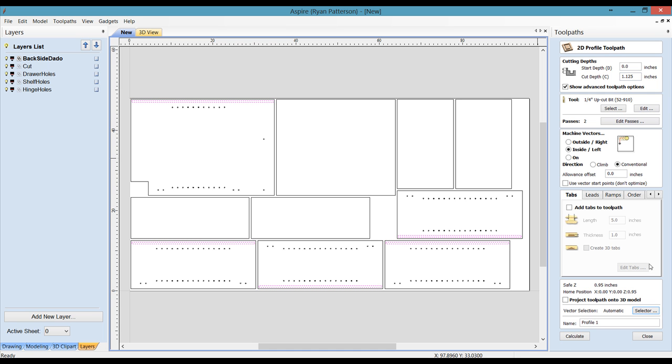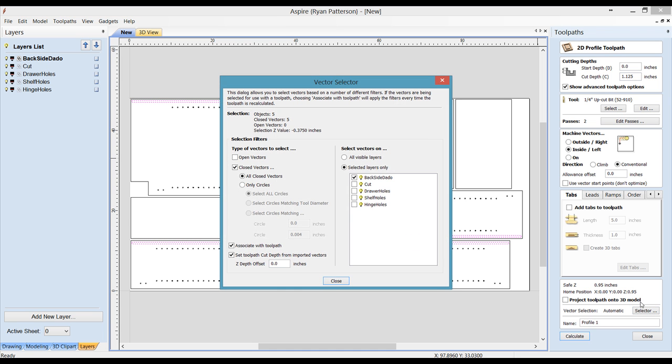So to do that, we're going to go back into the selector, and we're going to use Vectric's variables, T, which is for thickness. So if I just enter in T and hit equals, that's going to equate that to be 0.75. But remember, we need to subtract T. So I could just enter in a minus and leave it just as it is here, 0.75.